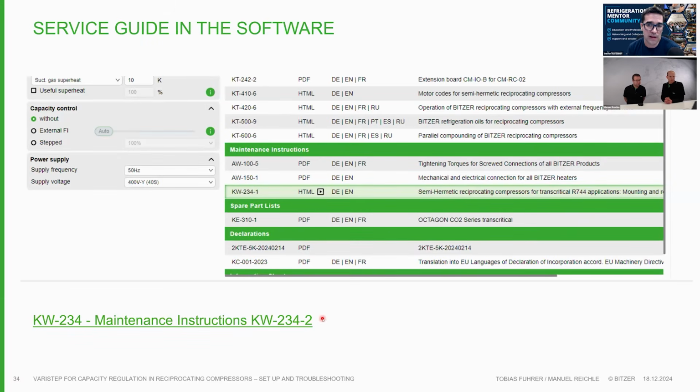One of the biggest things is that we'll have to do another one just on the wiring diagram, because that's so important. Their understanding of what to check physically in the IQ module. Yes, you have the best software and all this stuff is great, but you have to understand it mechanically. So this is using your meter. Does the compressor have the proper voltage? Does the IQ module have proper voltage?